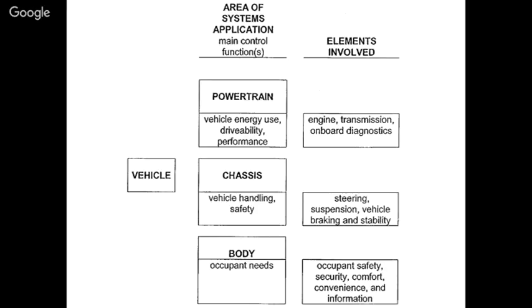Normally if we apply a brake, the car will decelerate at some rate. Whereas in case of accident, when the car hits something, the rate of deceleration will be too much. And the sensors will sense it, and before the actual impact occurs, the airbags will inflate, thereby protecting the occupants from hitting the steering or other parts of the car.